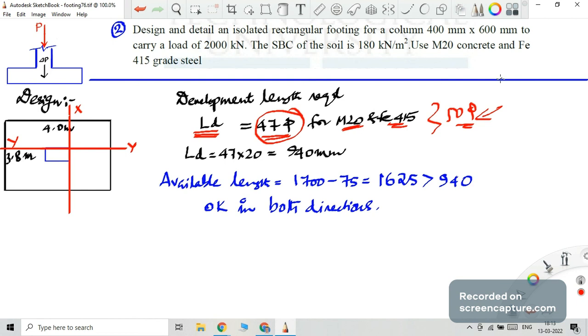Suppose you have a big slab or a big beam, say 20 meter as the dimension. But in the market, the reinforcement available is only of 8 meter or 12 meter. You won't get 20 meter long reinforcement in the market because that is to be transported by a truck or trailer. So whenever you try to fix the reinforcement for 20 meter, you need to lap it.